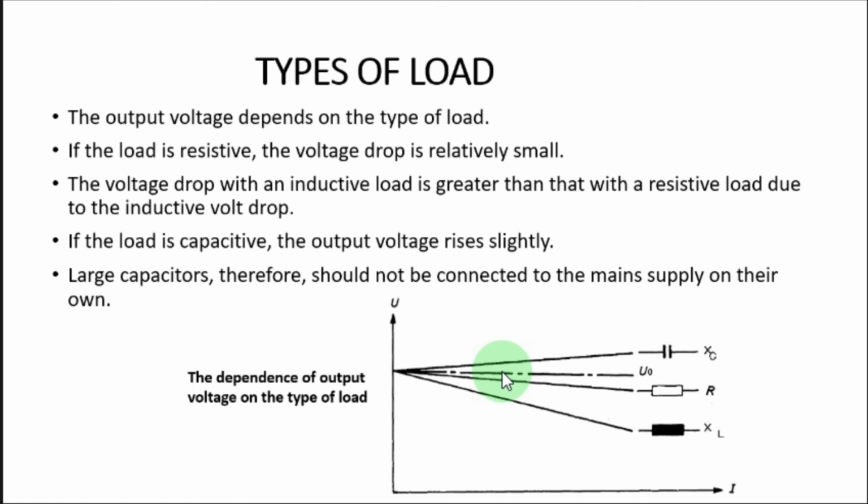And then efficiency means the ratio between output power and input power. That also you can calculate from the results of the tests here, because the efficiency you can measure by the output power divided by output power plus the losses.